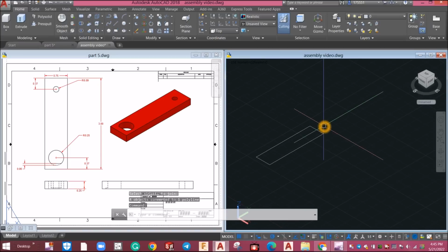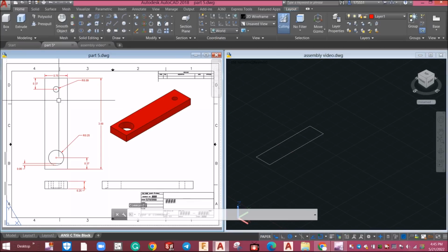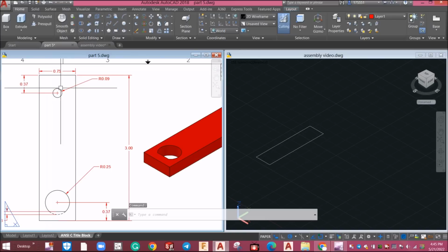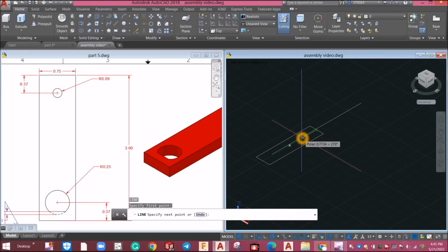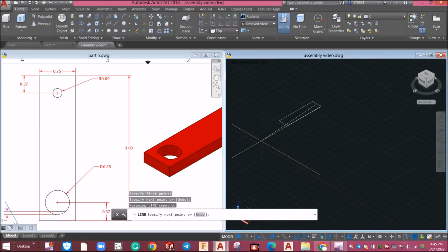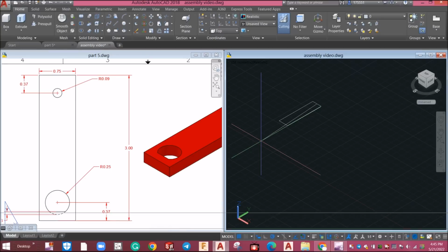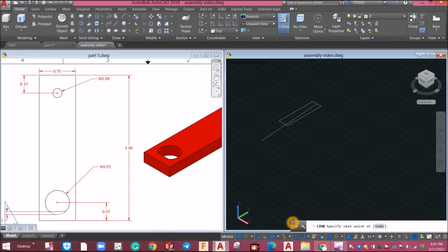and I'm gonna draw a circle. The distance from the center of the circle is from the midpoint to this point for 1.37. So line towards the direction, which is the x-axis. I'm just gonna put this one down. You can tell it by looking at the UCS. All right, so along the y-axis, enter 0.37.